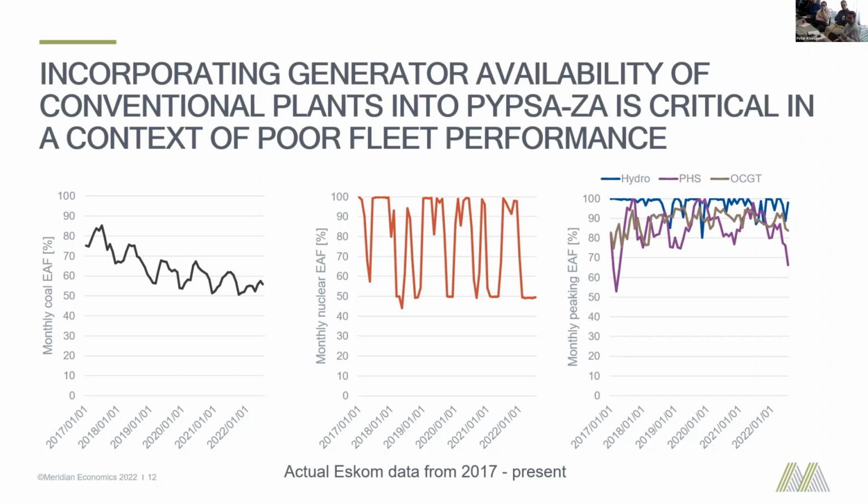This is the one area where Plexos has a step up on PyPSA, in that they have planned and unplanned maintenance scheduling built into the program. So you can tell Plexos that you need to do so much percentage of planned maintenance, and then it will allocate that across the year. At the moment, we're just imposing the actual data, and then we can project that forward to say it's going to be the same, it's going to get better, it's going to get worse. But we definitely have an interest in possibly doing our own pre-optimization that does some of the maintenance scheduling down the line.